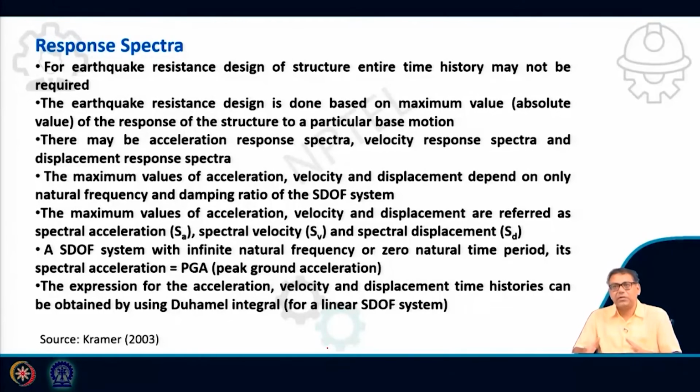Okay, as we know, there are these parameters: acceleration, velocity, and displacement. So there can be acceleration response spectra, velocity response spectra, and displacement response spectra. The maximum values of acceleration, velocity, and displacement depend only on natural frequency and damping ratio.